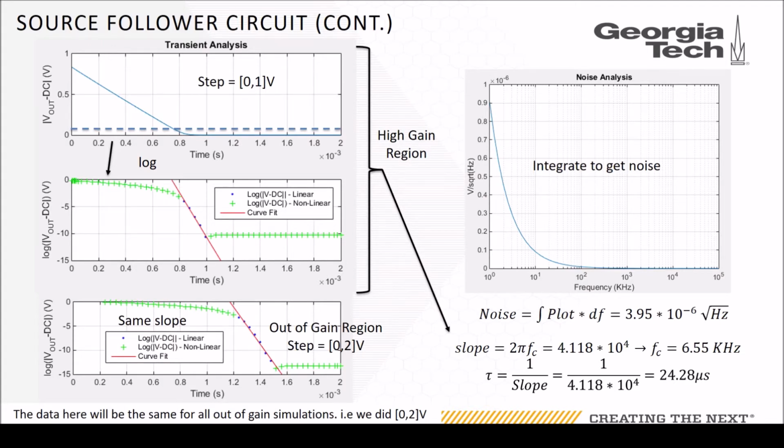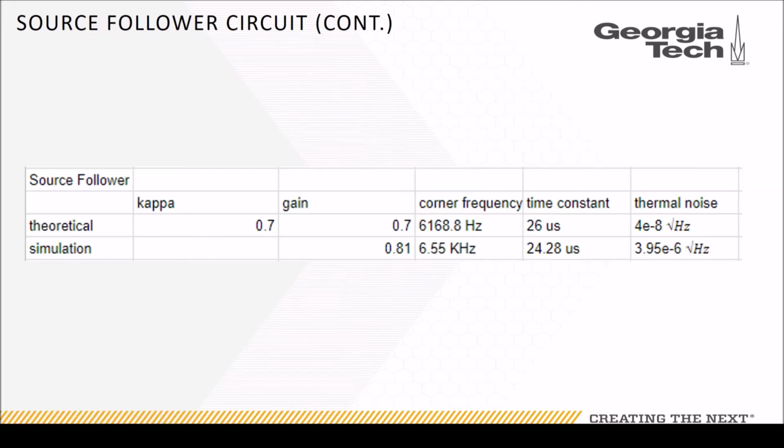And then you can also see we did noise analysis. We integrated over frequency to get our noise plot, and that gave us basically 4 times 10 to the negative 6. You can see our theoretical results agree very closely with our simulated values.